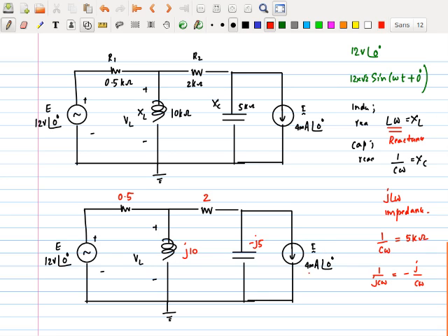So, which means this is an RMS value. A very simple way of doing this is, if they give you the reactance, if it is an inductor, just put j times the reactance. If it is a capacitor, you put minus j times the reactance. That's all. Right? If you don't want to think about anything, but I don't think you should do that. You should think to yourself and say, whoa, this is minus j5 because of that. You may not write it down, but in your head you see the j's all flying around and then you put it down as minus j5. Don't be like this guy who's just going in and putting j5 without asking anything.